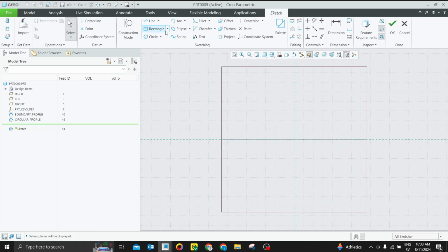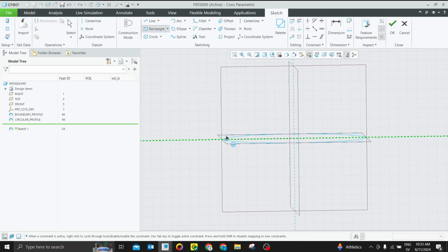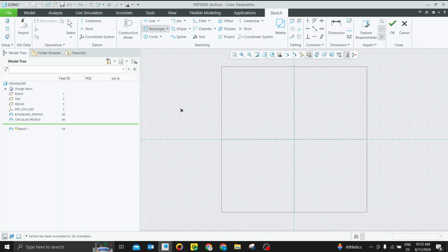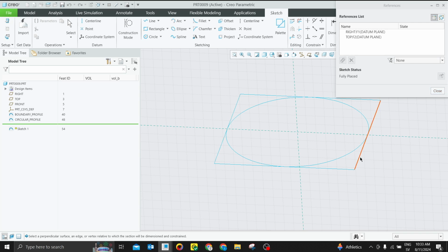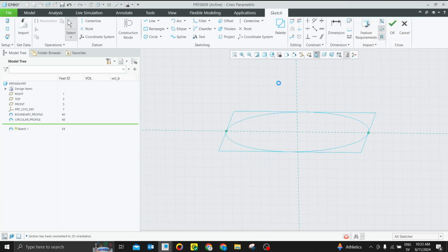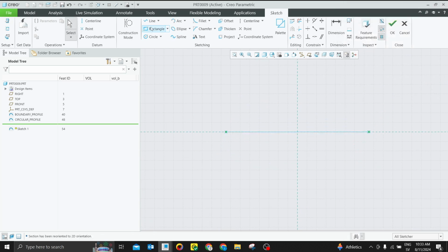Here I'm going to use corner rectangle. If I go view like this, and let me hide planes, I want to reference my boundary like that. This is the power of boundary to make your models parametric. Therefore, like that, I just need to dimension just height.